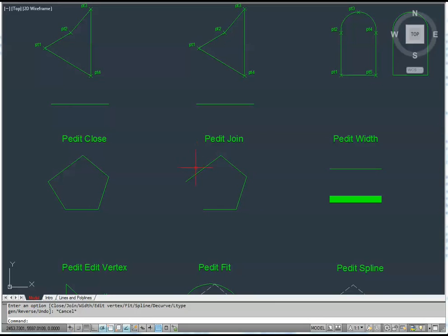So far I've been clicking on objects individually, which can become quite tedious. There's two other basic ways of selecting objects in AutoCAD. One is with the crossing window, which is starting from the right hand corner and moving up to the left, and you'll see it's a green rectangle or green marquee with a red outline, and that will select objects that the marquee crosses over.